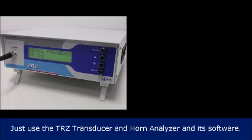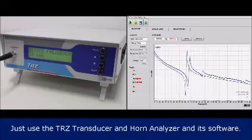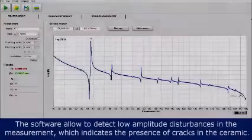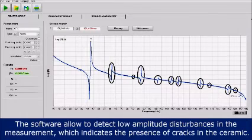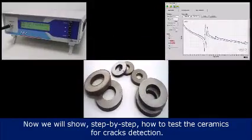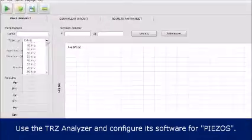Just use the TRZ transducer and horn analyzer and its software. The software allows to detect low amplitude disturbances in the measurement, which indicates the presence of cracks in the ceramic. Now we will show step by step how to test the ceramics for cracks detection. Step 1. Use the TRZ analyzer and configure its software for pieces.